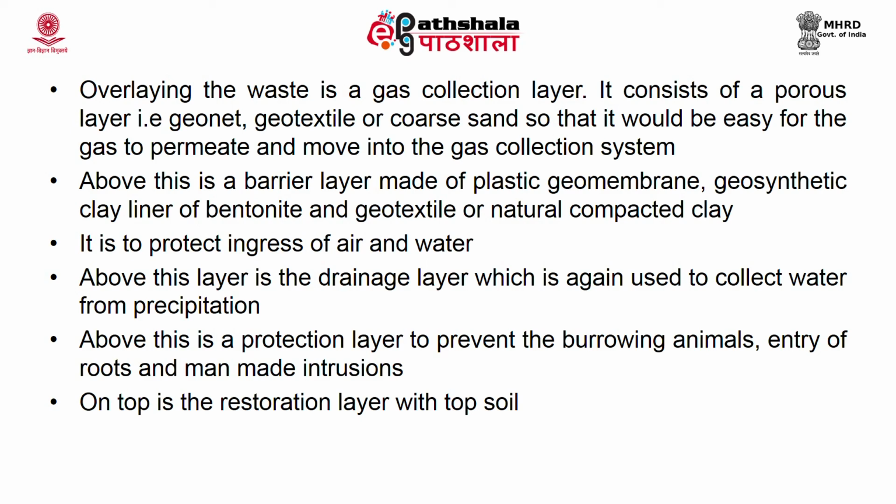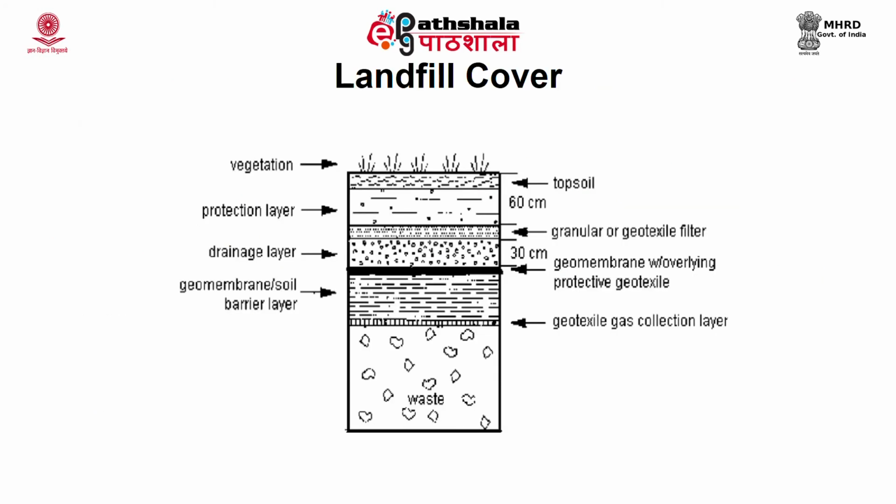The main purpose can be for beautification. So, overall if you see the cap layer, waste will be there, on top you have a gas collection layer, then on top you have a barrier layer, and then you have a drainage layer, protection layer, and on top you have a layer of topsoil, which is called a restoration layer. Now, this is the structure of a landfill cover, where you have waste, then you have a gas collection layer, then you have a barrier layer lined with a geomembrane, then you have a drainage layer, which is again lined with the geotextile, then you have a protection layer, and you have topsoil, which is used for vegetation purpose.